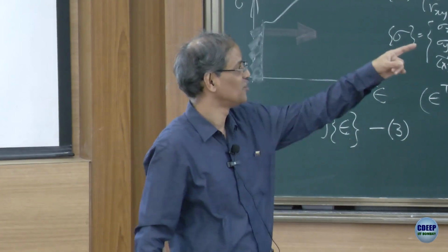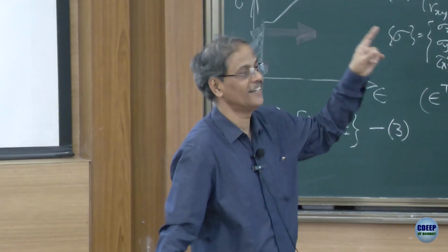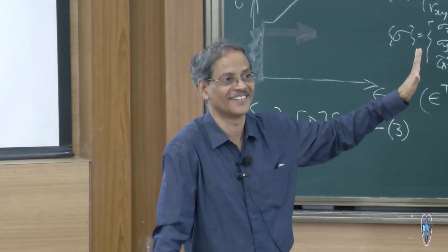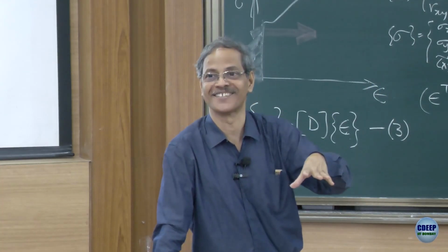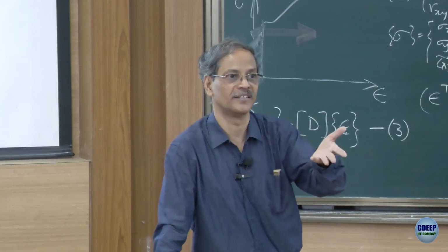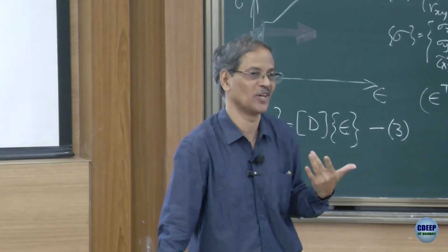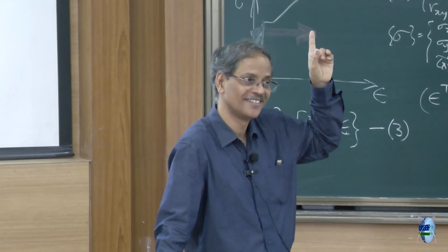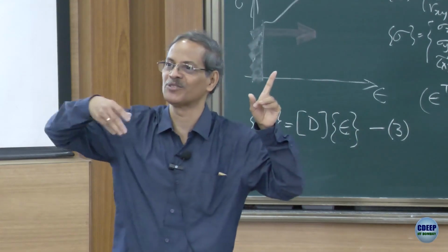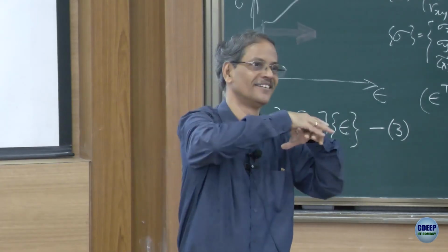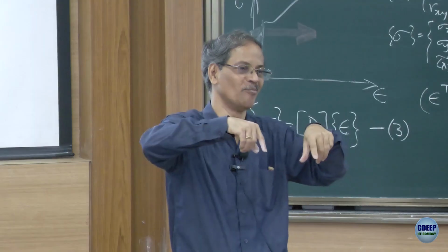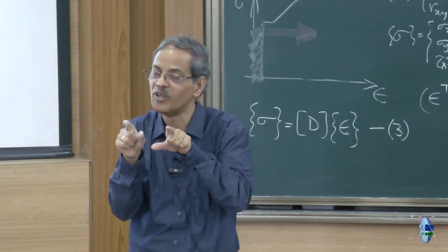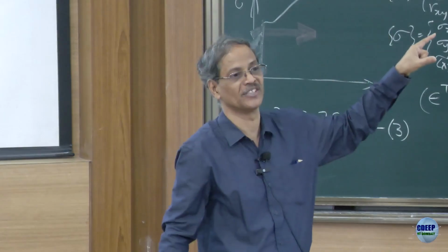Then here the cross coupling between mechanical and electrical terms has to be brought into the energy expression. I have not considered anything like that. You have shape memory alloys. Those of you who are thinking in terms of using shape memory alloys for your designs and all that. It remembers that at this temperature I was like this. If you change the temperature, mechanical deformation, whatever, when you bring it back to that, we might forget, but that fellow remembers and then tries to go back to its original shape. So, all that will be captured by changing these energy expressions.